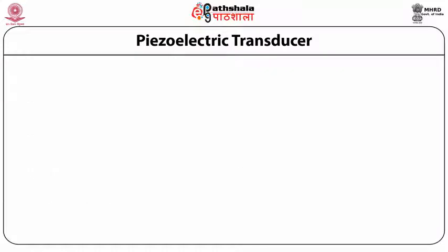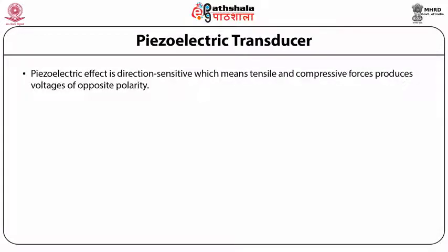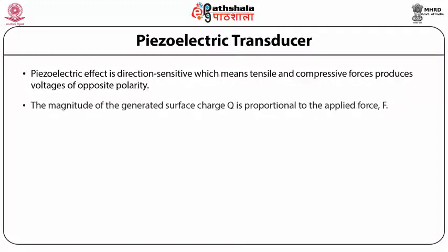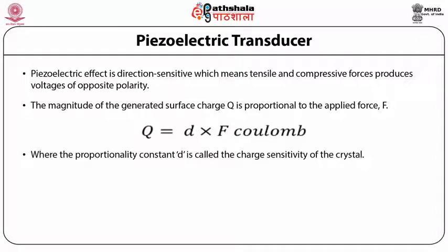So let us now discuss the piezoelectric effect. The piezoelectric effect is direction sensitive, which means tensile and compressive forces produce voltages of opposite polarity. The magnitude of the generated surface charge Q is proportional to the applied force F. That is, Q equals D multiplied by F coulomb, where the proportionality constant D is called the charge sensitivity of the crystal.